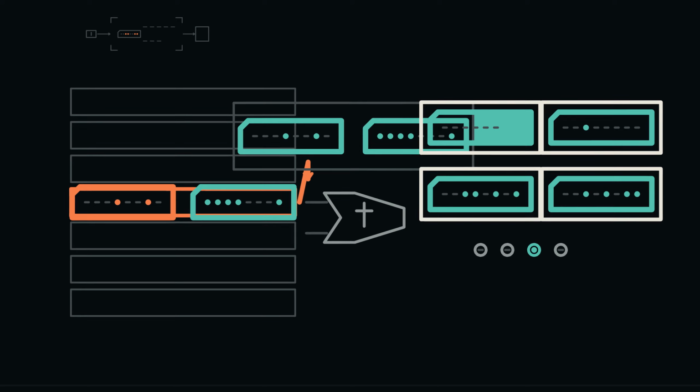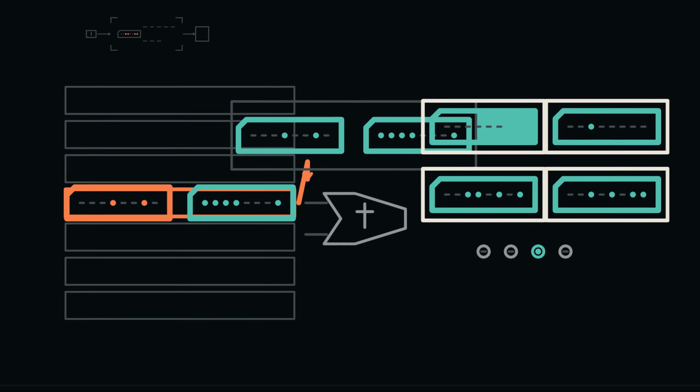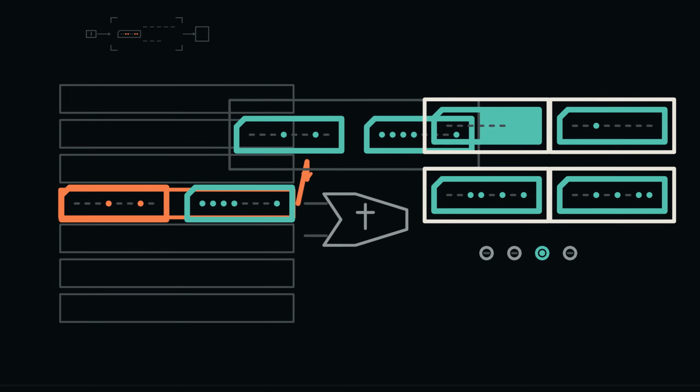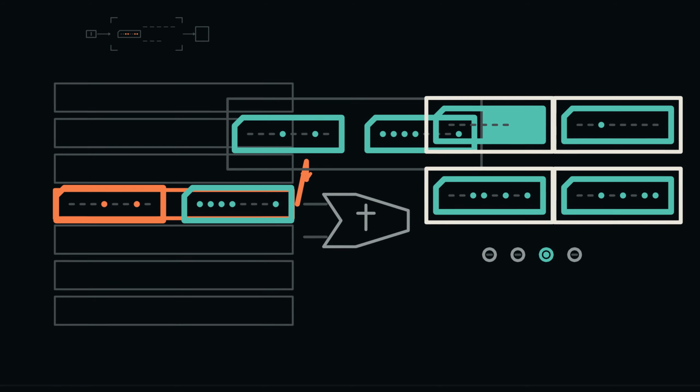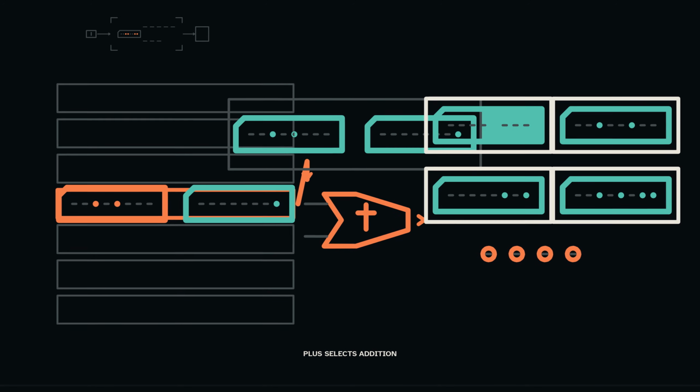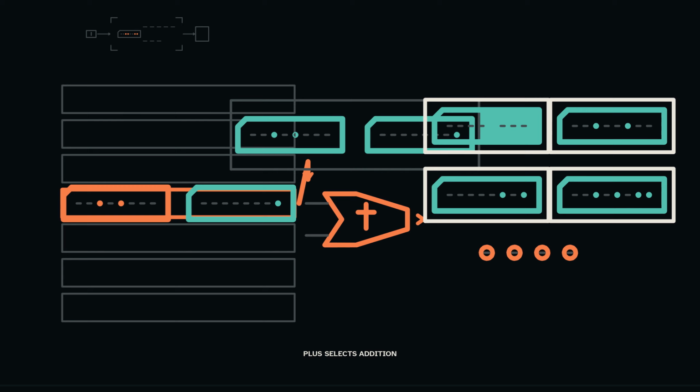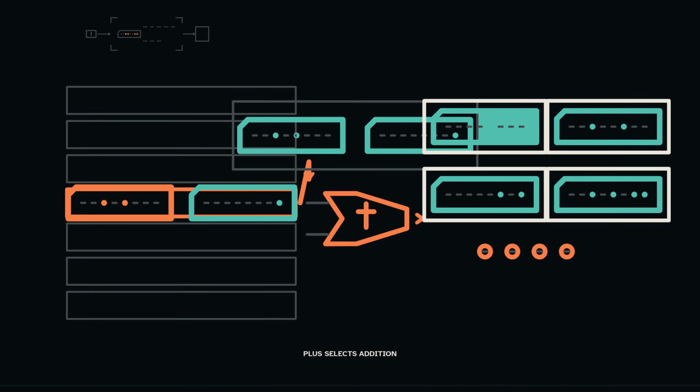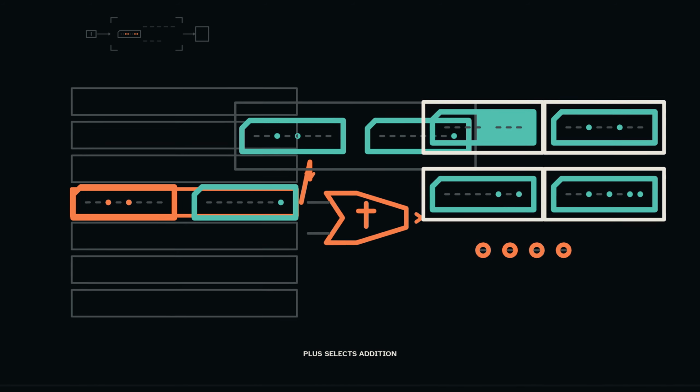Numeric 3 remains in R0, the validated plus code remains in R2, and the text code for 5 is in R1. Subtracting hexadecimal 30 from the byte in R1 produces numeric 5. The addition instruction then names 2 registers.